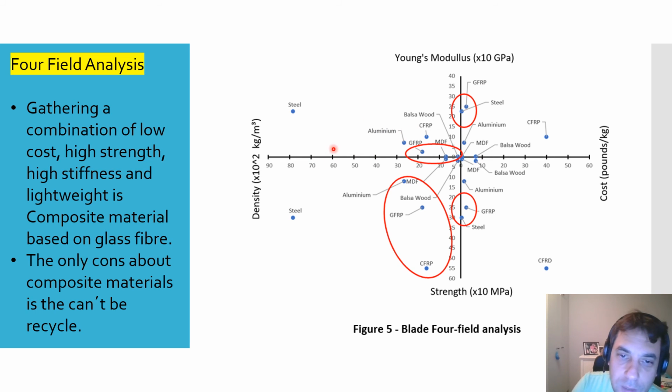Talking about less weight and also stiffness, stiff enough, as we did before, making that index that regards the elastic modulus and density of the material, in that preview we get that balsa wood has really the biggest index possible.